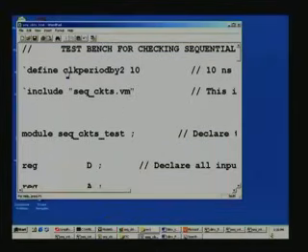So, in the test bench we have to include this .vm as I mentioned. This is a change from the design file, which was just .v, to this .vm which was created during synthesis. This is the optimized file, and we can even have a look at this file if you wish later on. Right now let us open the ModelSim.